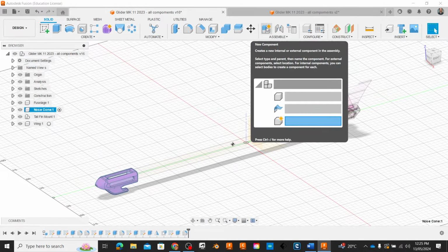So I'm just going to activate the whole component so I can select that part of the sketch. And then I'm going to go Control-C. All right, I'm going to let that sketch sit there. I can turn it on and off if I need to. So I shouldn't be able to see that. I'll turn my other components back on. I'll home my view. Then I'll re-sketch on here and then paste that sketch profile into place and it'll go into the right orientation.